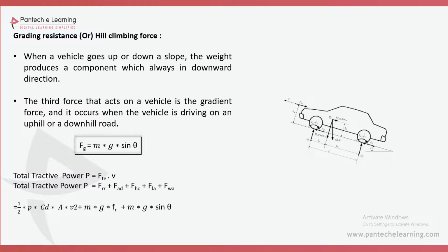This gradient term is not necessary when a vehicle drives normally. When your vehicle descends or drives in a hill station, you have to consider the gradient resistance. Otherwise, when a vehicle drives in a linear direction only, there is no need to consider gradient resistance.